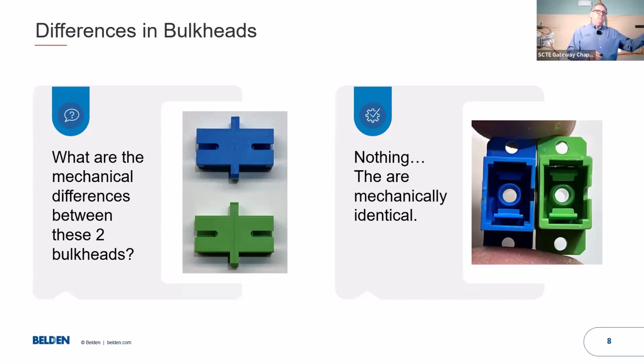In house boxes, in head ends, test jumper type things, if you're trying to make fibers reach, there are bulkheads. Bulkheads are like F81s in the RF world for putting two types of fiber together. The color of the bulkhead doesn't matter. It's still just a straight through device, right? Like if it's inside a house box, one side of the cable is going to be green, so you put the other one green, it looks nice.